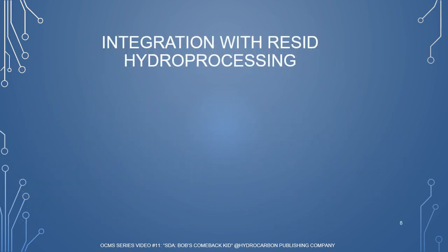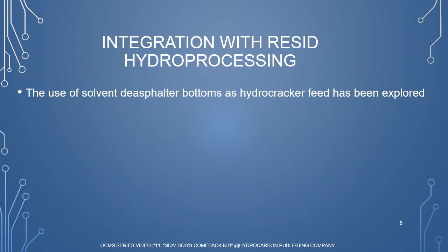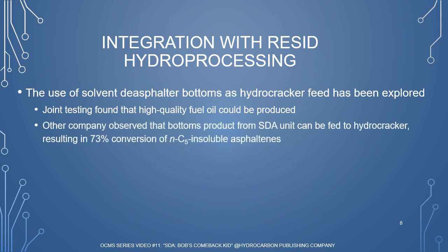Using the solvent deasphalter bottoms as hydrocracker feed has been explored. Joint testing between two companies found that high-quality fuel oil can be produced. Another company found that bottoms from an SDA unit can be fed to a hydrocracker, resulting in 73% conversion of